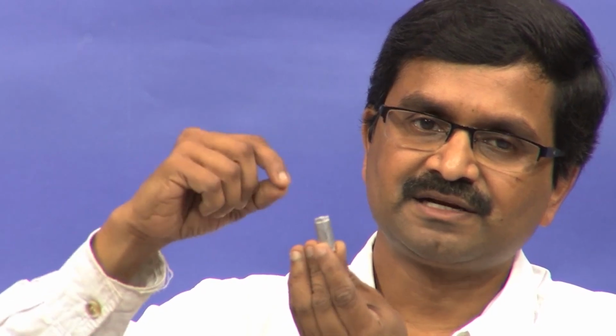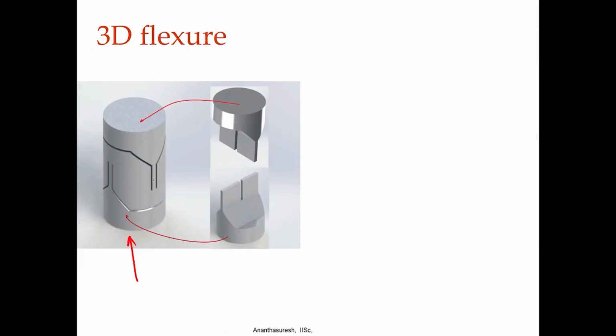So, if I attach a body here related to the base, this little cylinder with those couple of cuts can tilt like this and tilt like this. This has an interesting feature that you cannot tilt more than a certain angle, because if you come back to the slide, we can see that when it tilts, this is going to just touch. So, over here when it tilts, it is going to touch the other surface, it cannot move much. There is limited motion, but it is going to be strong because it is not going to be excessively deformed.